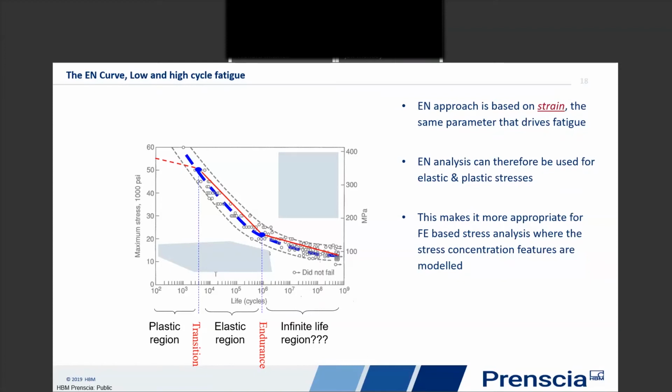I need to have some way to predict plastic strains, either a nonlinear FE analysis or corrections on the loading. The curve itself now is not nearly as easy to interpolate. And so strain life is very difficult to do by hand. One reason we tend to migrate to stress life whenever we can.